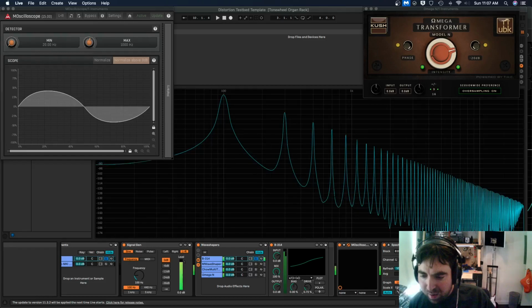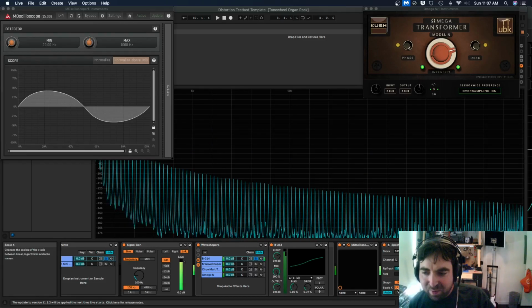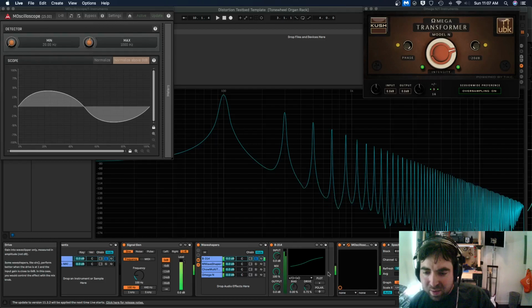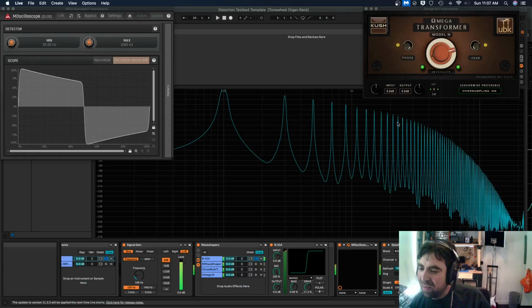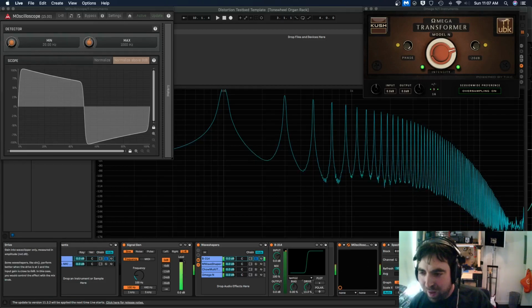And in the linear plot, it looks even crazier. You can see there's some aliasing down here as well as it's folding back. One nice thing about tanh is the roll-off of the frequency response is quite controlled, and I think quite natural sounding. It's not quite as bright, but if you look down here, we're at like negative 168 decibels, so that's well below the noise floor. We don't care about anything down there, so we can apply some gain.